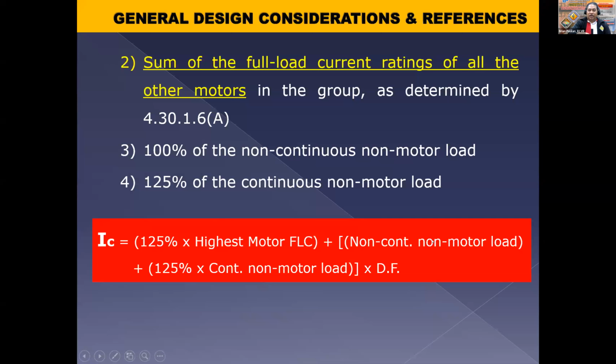So basta the thing is highest motor load times 125% plus sum of other motor loads. And then ito yung 3 and 4, no? So ma-follow rin 'yan. Okay.